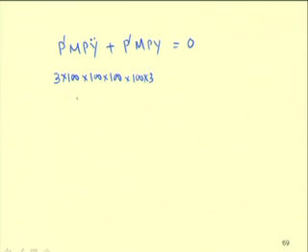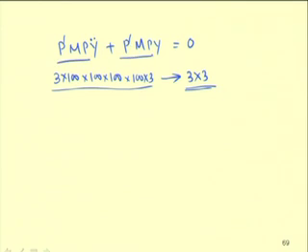So this finally reduces to a 3 by 3 matrix. Instead of solving the 100 by 100 matrix, one can solve this 3 by 3 matrix. All these matrices will be 3 by 3. So, one can solve these 3 equations to find the solution or response of the system. This method is known as normal mode summation of the system.